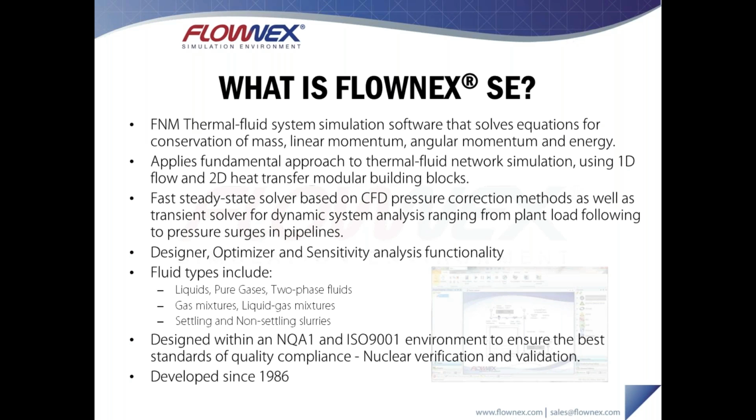When we contrast that to the CFD and FEA world, we see that the FEA and CFD world tends to focus on detailed local component modeling. So the geometry involved is typically smaller due to the increased computational expense with the much finer meshes. The software itself also runs in both steady and dynamic simulations.